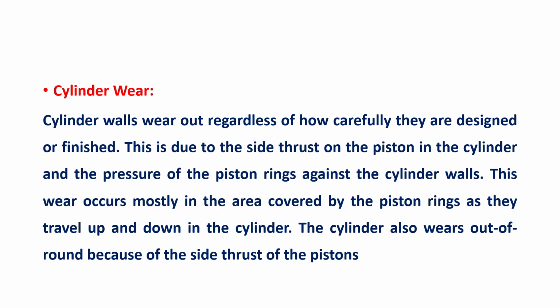The reason here is that the cylinder and pistons are hotter and exposed to more grit at the top than at the bottom. So the wear will be accelerated at the power strokes. That is very essential.